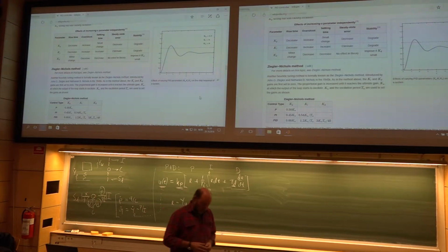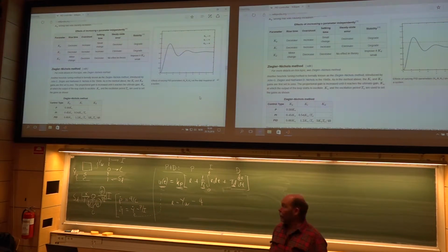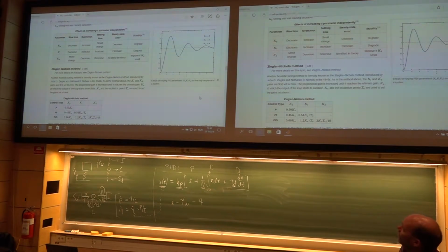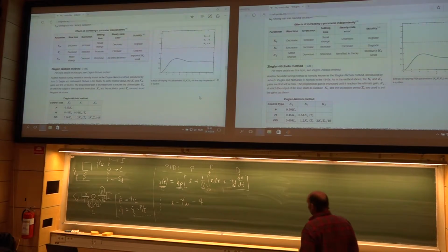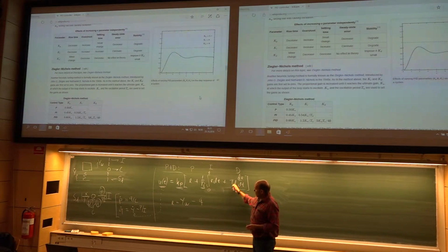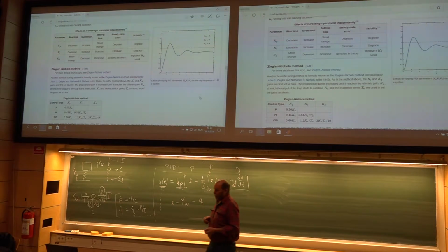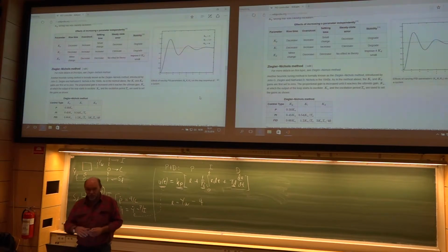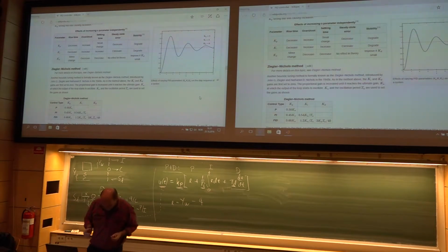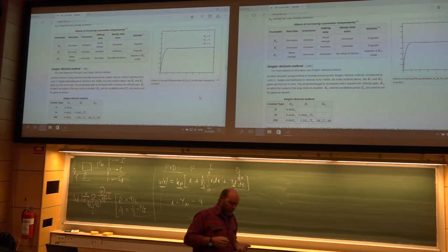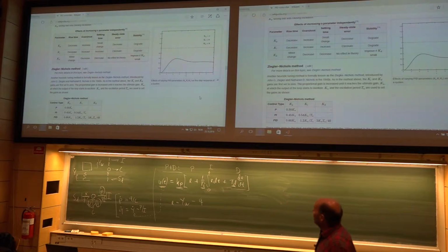So he says, start with the proportional constant, the KP. Then afterwards, you adjust the time, and finally the integral, and then finally the derivative. And you should do so for the first one to have at least starting to get some oscillations. And when you get stronger oscillations, you should halve the proportional constant. That should be the first step.